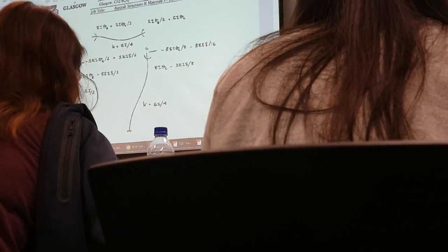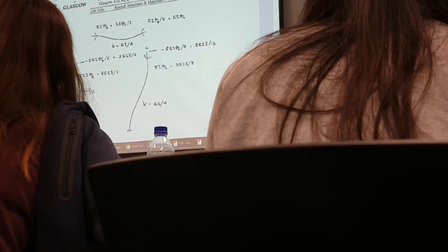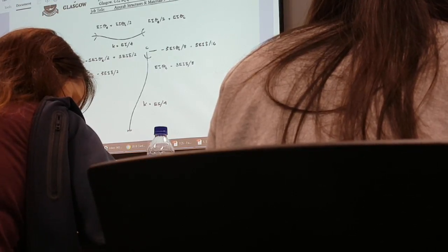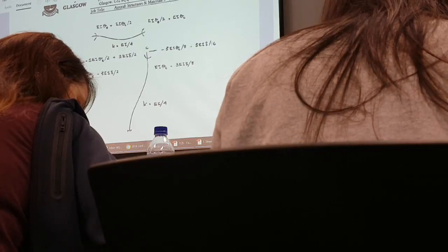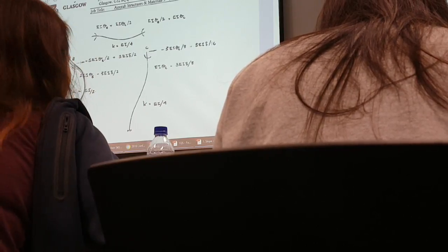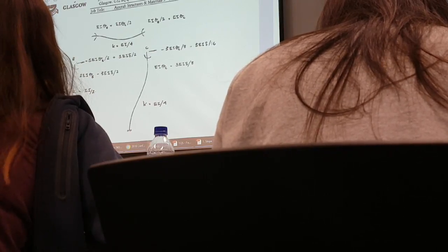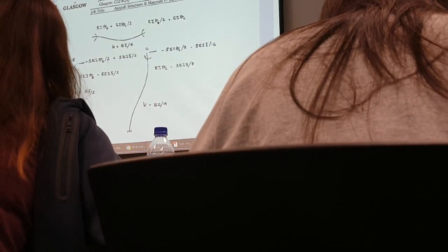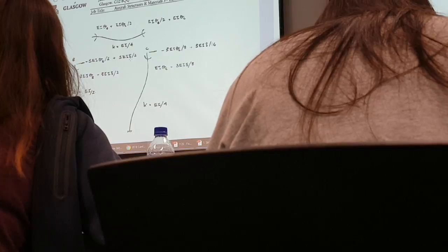And then for this force over here, of course, it has to be minus PY2. Correct? If you want to use the formula, use minus PY2, and you follow the formula. Eventually, when you work it out, the force in node B will be minus 3E theta B divided by 2 plus 3E delta divided by 2.